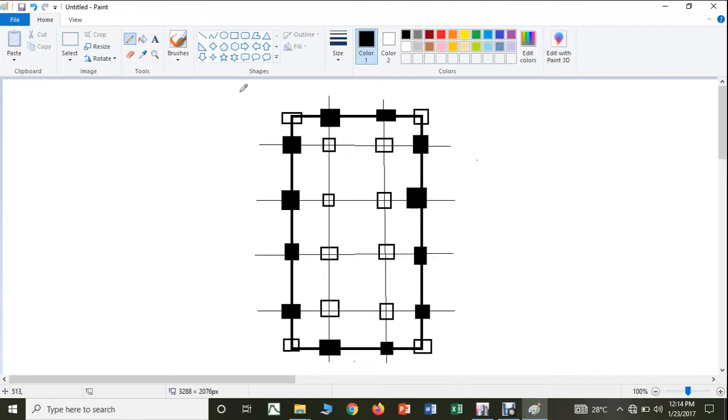Now if I take this one, which is in red color, we have to design it as a biaxially loaded column. Why biaxial? Because the moment developed here has no beam on the other side to nullify it, so that moment will come to this column.